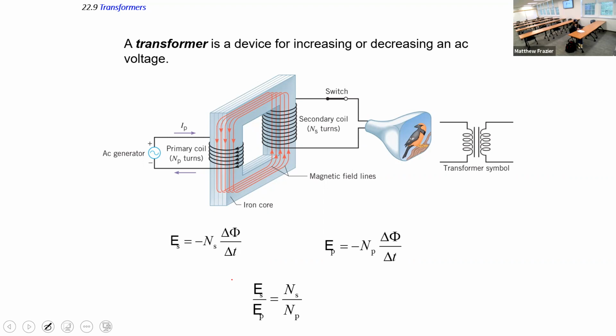And so in this case, the idea is that the magnetic field is almost completely confined to this iron core. And so what's happening is we have some current flowing, and it's an AC current from some sort of alternating voltage source. That's going to cause a change in flux through itself. Or you can calculate as the current varies, then the magnetic field generated by the coil varies, because all these coils are B = μ₀Ni.